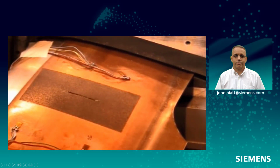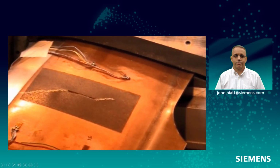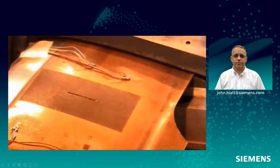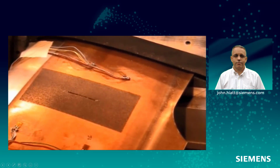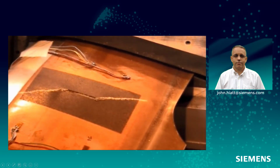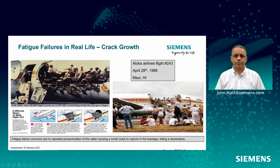So here's some crack growth. They do this a lot in the aircraft industry. We load it, the crack propagates. The crack will also propagate from a cyclical load. It'll start to grow, and they want to know how it grows. But once they see a crack, they're saying, hey, this thing isn't going to come apart anytime soon, so why should we replace it? We're going to have a maintenance schedule, we're going to monitor this, and we'll replace it at a certain time. That's crack propagation.